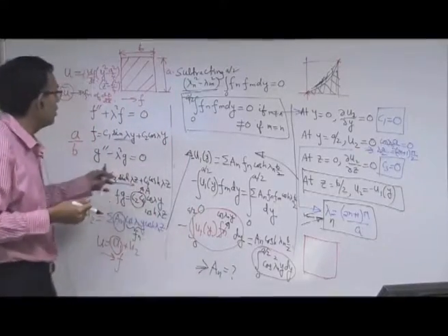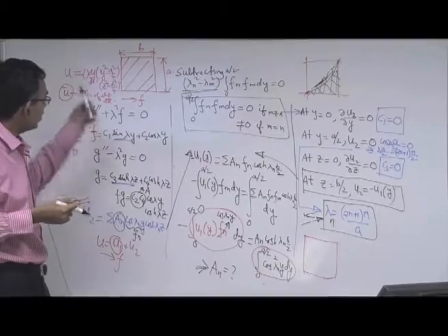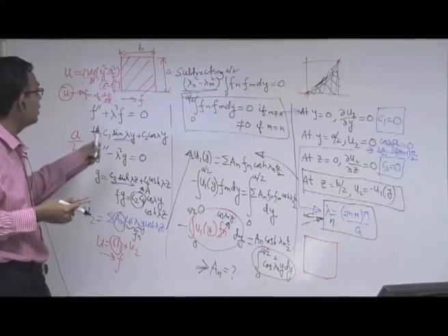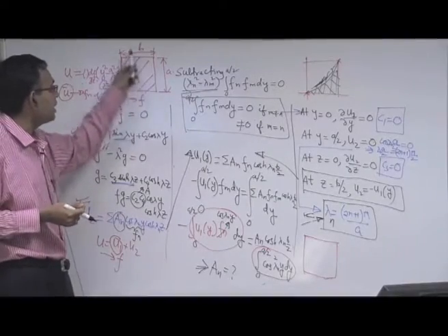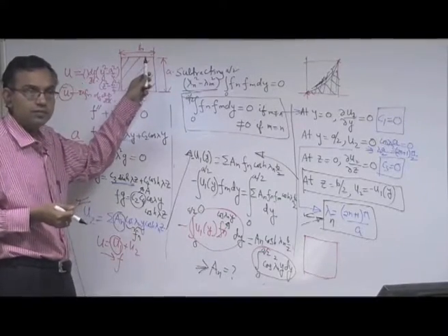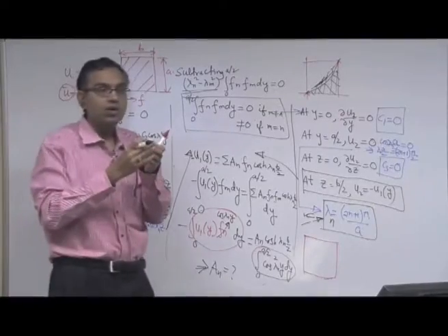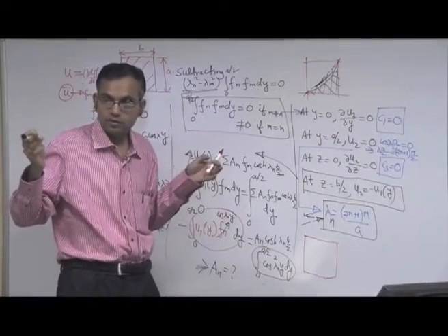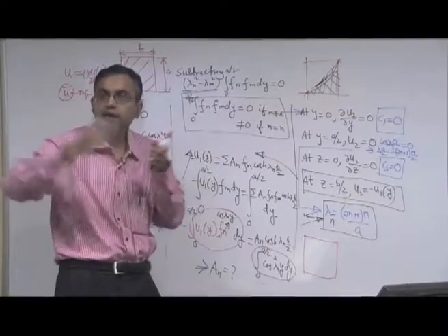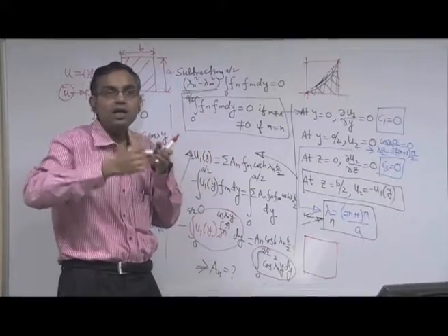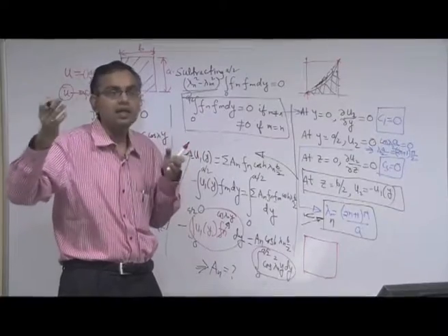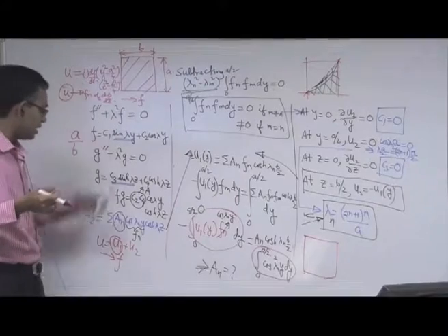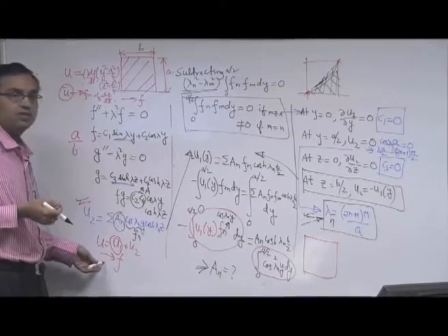So here also you will see that there will definitely be some error, and the error will be perhaps most severe when the aspect ratio is perfect, that is A is equal to B, because then it deviates most prominently from the parallel plate channel case. But otherwise if you take other limits, either A by B tending to 0 or B by A tending to 0, that makes a parallel plate channel case, then this friction factor and this friction factor calculated from here should match.